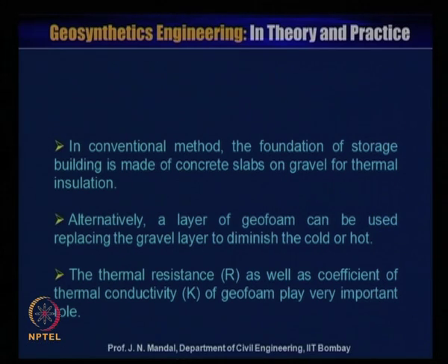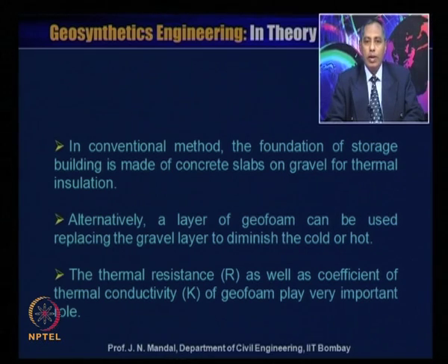In the conventional method, the foundation of a storage building is made of concrete slab on gravel for thermal insulation. Alternatively, a layer of geofoam can be used, replacing the gravel layer to diminish the cold or hot. The thermal resistance R as well as coefficient of thermal conductivity K of geofoam play a very important role.